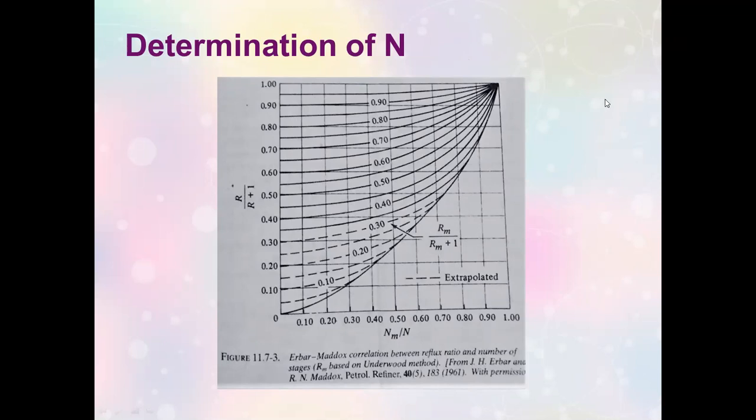So I mentioned to Joshua that that's just the very crude way of us finding the x prime and y prime. That way you can find the R minimum. I hope you still remember what you studied, that in order for you to find the minimum reflux ratio, there's a need for you to find the x prime and the y prime. And that's how I gave you the instruction, and that's how you should find the x prime and the y prime from the intersection of the EOL and the Q line.